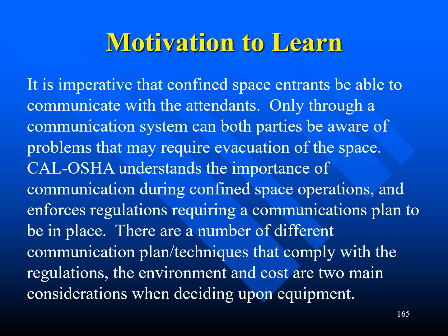Why is this important to us? It is imperative that confined space entrants be able to communicate with the attendants. Only through a communication system can both parties be aware of problems that may require evacuation of the space. Cal OSHA understands the importance of communication during confined space operations and enforces regulations requiring a communications plan to be in place. There are a number of different communication plans and techniques that comply with the regulations. The environment and cost are two main considerations when deciding upon equipment.